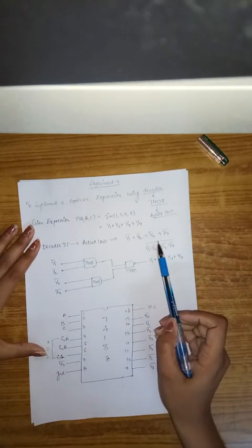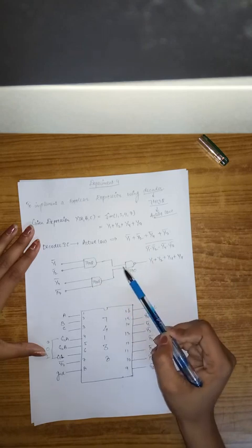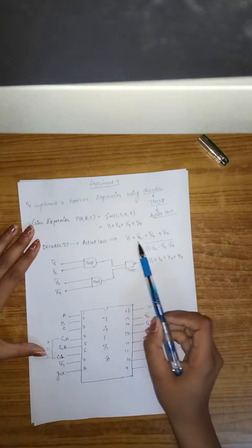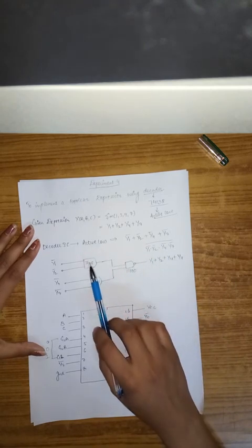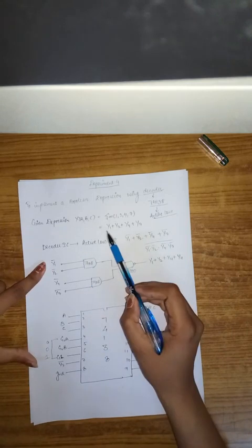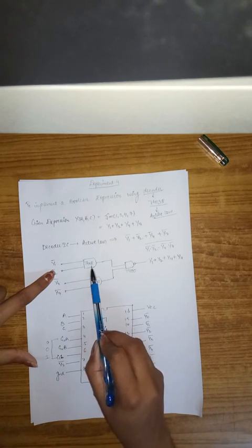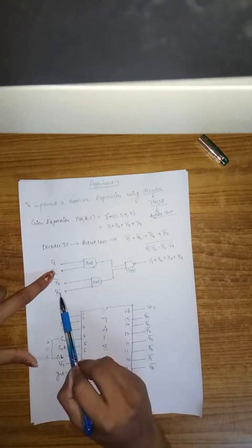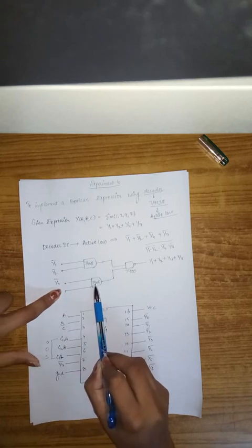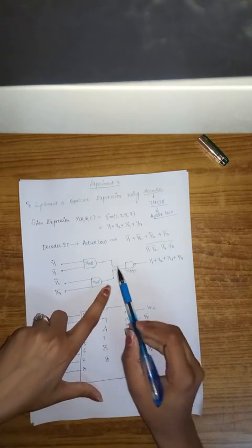So we will be using an AND and NAND combination for converting this active low to active high. Now one of our inputs is Y1, Y2, so we will be giving Y1 bar and Y2 bar as input to an AND gate IC, which is 7408. Y4 bar and Y7 bar go to another AND gate, that is 7408. Next, we will be connecting this to a NAND gate IC.